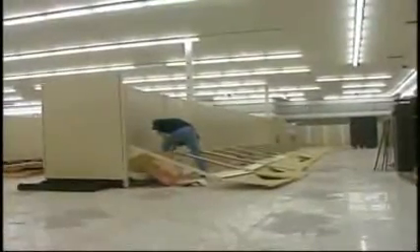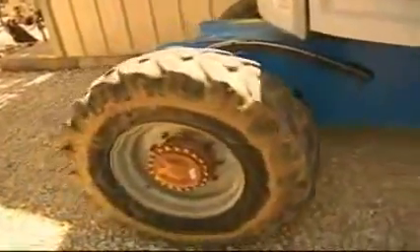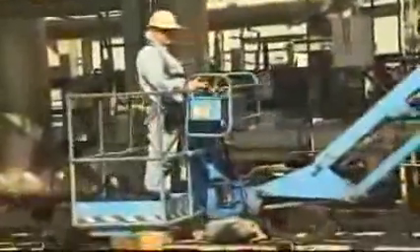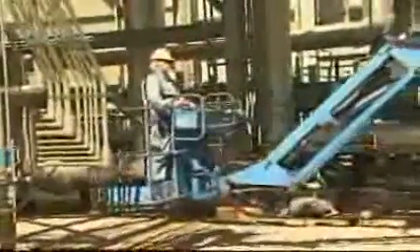It is necessary to always inspect the work site prior to using the lift. The ground on which the lift will be used needs to be solid and as level as possible. Do not use a lift on unstable ground. Hazards that may create dangerous driving conditions, such as overhead power lines, holes, drop-offs, bumps, lumber, tools, and debris, must be identified, and procedures to avoid any hazards made known to all employees.